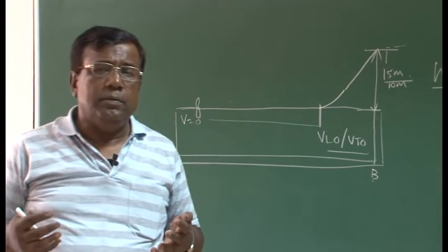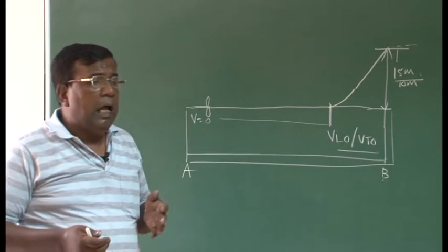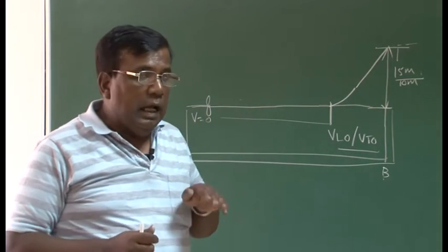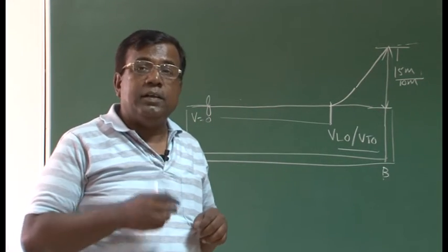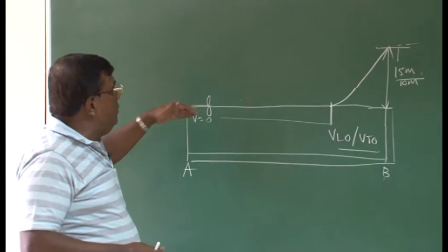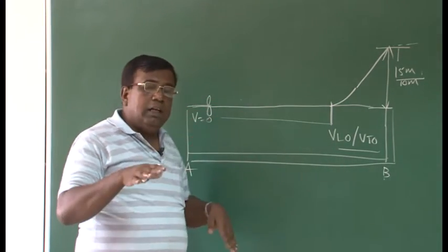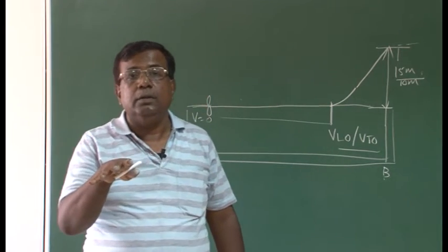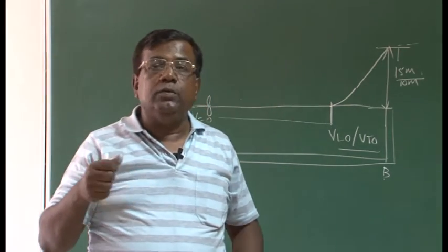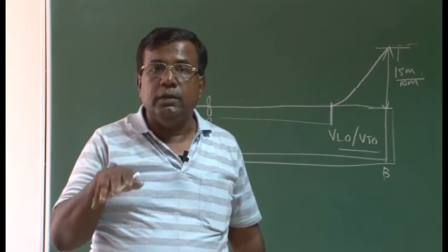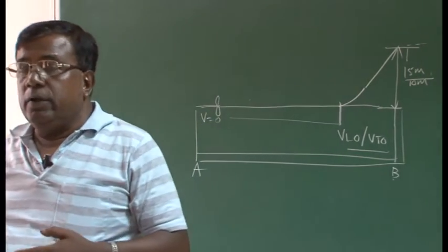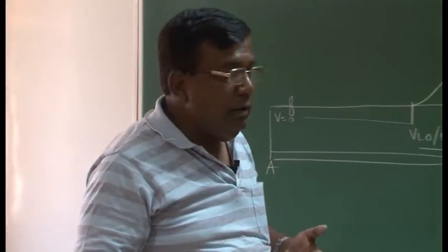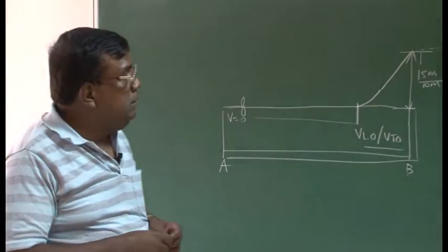For example, at what speed the elevators will be effective, at what speed the rudder will be effective. Imagine on the ground, I want to steer the nose wheel. I want to turn on the ground. How do I do that? I use rudder and turn the nose. But for rudder to be effective, there has to be some defined speed, so that the pilot should know.